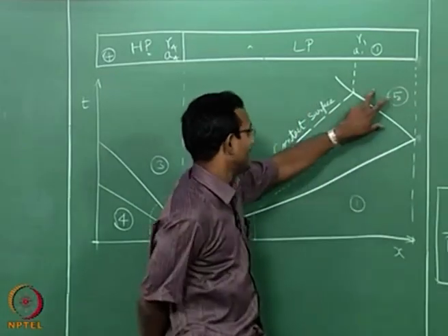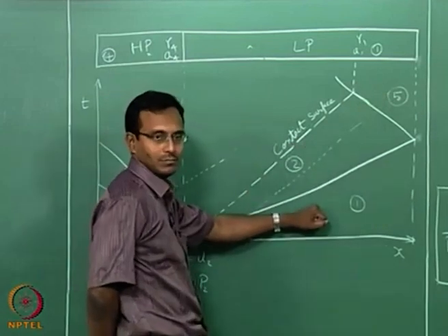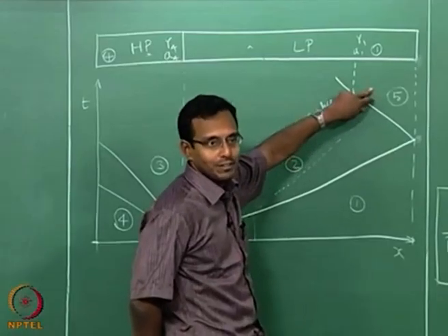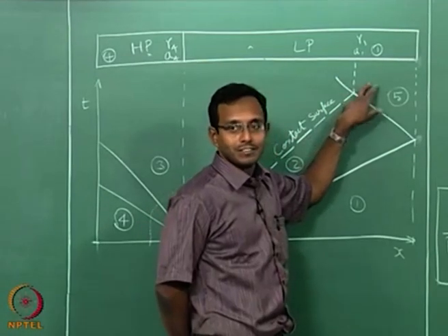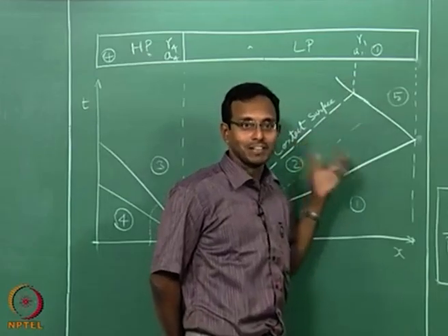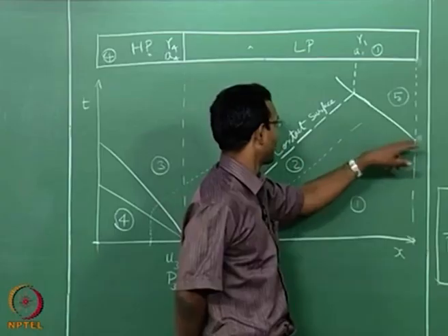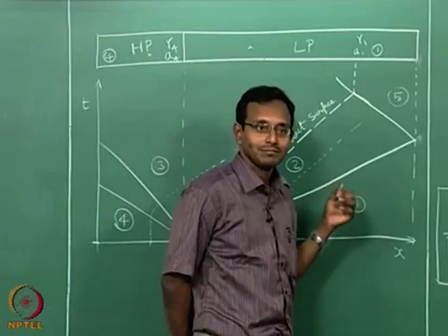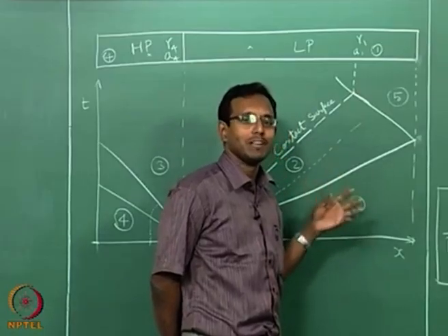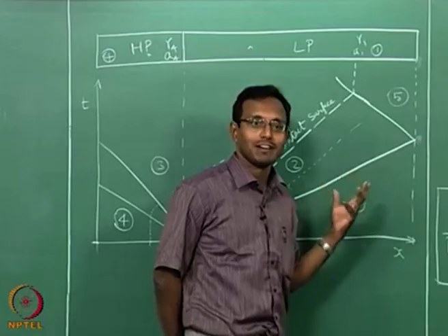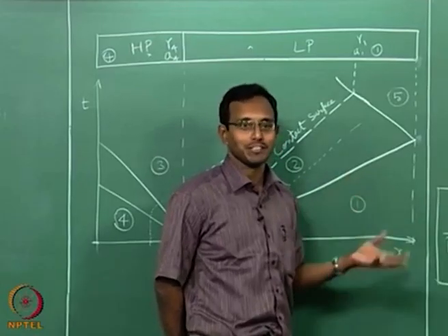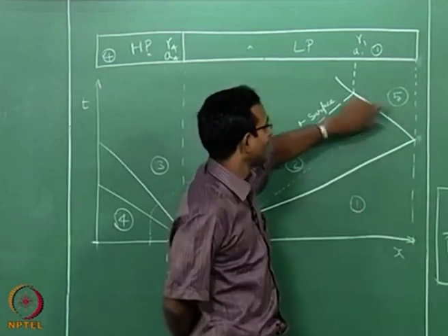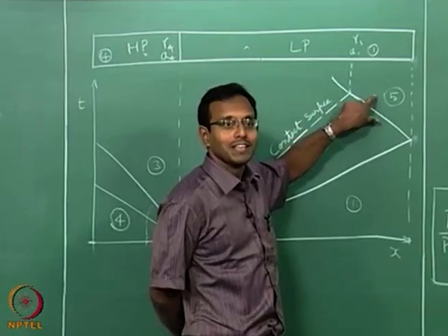So I have finally taken my gas at 1 to state 5, just T5 P5, and now I can study suddenly pressurized gas at a very high pressure and temperature. Okay, it has been processed by 2 shocks, and all this is happening in microseconds time scale. Within say 100, depends on the length of the tube, of course. It could be anywhere in the order of 100 to 500 microseconds. Okay. So that kind of time scales. Within that time it got compressed. Now I can sit and wait for some time.